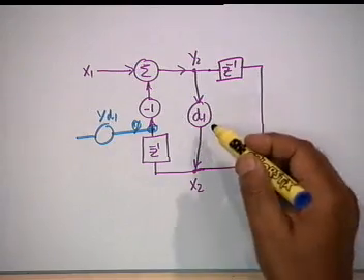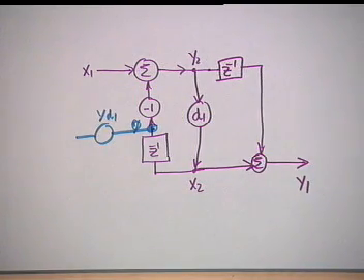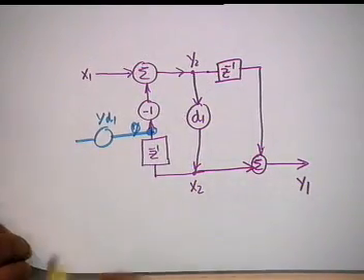What are you doing now? You are increasing the number of multipliers. You require a d1 and a 1 by d1 here. That's worse. Multiplication by 1 by d1, so that's not a solution. You can try others. If you can find out a modification of this so as to have only one delay, you have done an original work. We should shift d1 after z inverse. Try the solution and let me know. If you can do that, you have done an original work.